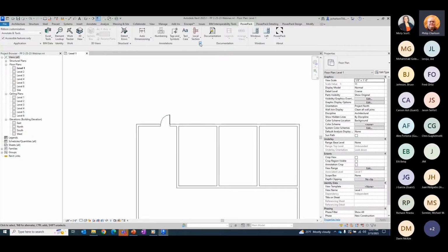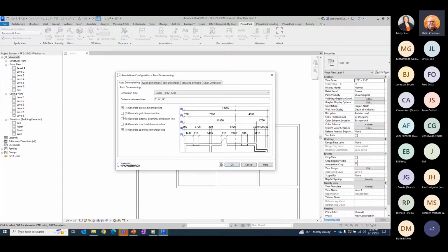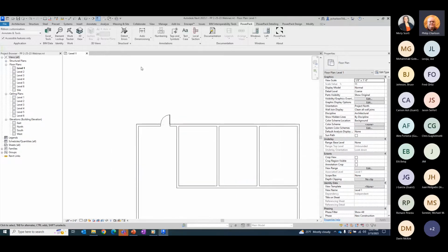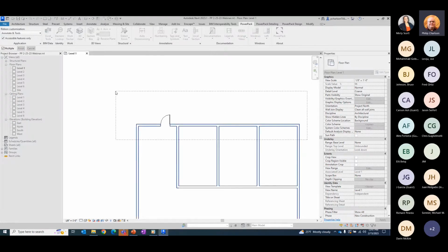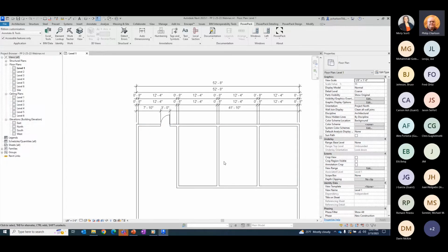So very easy to go in and pick that information. Let me wipe these out, and we go back to our tools here. Let's go in and choose all of our components. Let's see what happens if we get all of those. Let's see if we can break it, huh? All right, so I'm going to window select all my objects there again. We'll hit enter. You can pick it off of this one, pick up here, and you can see we get all of the possible scenarios for dimensions within there.